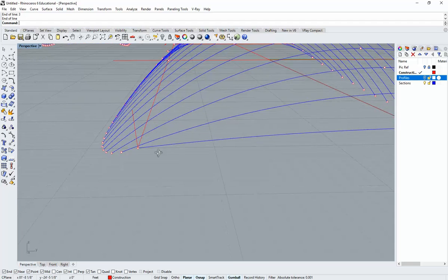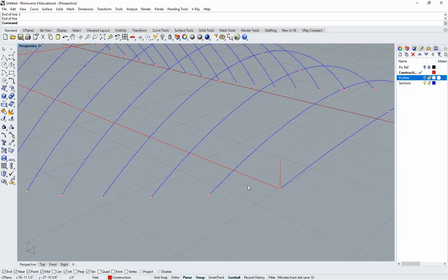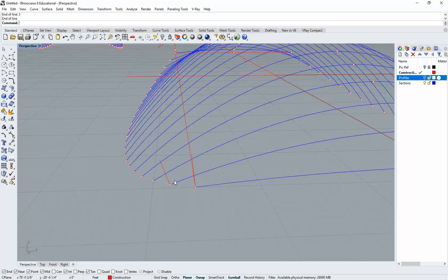So this part gets a little bit repetitive. I'm going to do one more as a demonstration, then I'll pause and let you guys work. So once again, it's line, perpendicular, start at the end, type in F, hit enter, type 2 or 3, whatever, hit enter, hold shift, click when it's in the Z direction. And you've drawn your perpendicular curve.